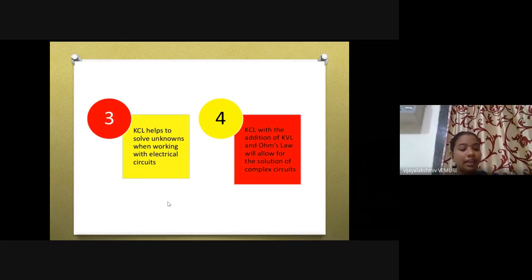Okay, so in the KVL method or mesh analysis method, what is the solution you first derive? You have derived the loop currents, isn't it? Once you get the loop currents, then you are able to find out branch currents and the voltages across the branches.